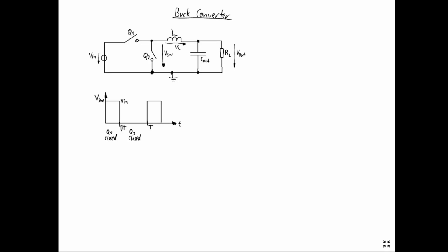A buck converter reduces the input voltage. For accomplishing this, you can think of it as two switches, which alternate between the input voltage and ground. Now, only an LC filter is used to get a smooth output voltage and current.